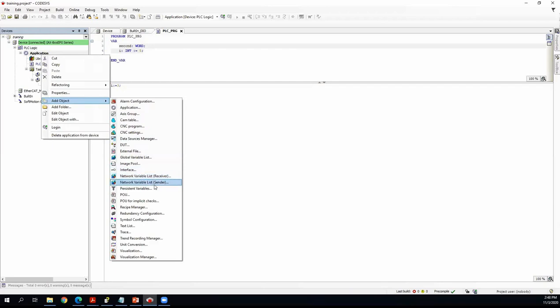This, for instance, is the Ethernet IP communication interface for object-oriented programming. This one is for OPC UA. So there are many tools and apps that you can use. For another program, we need to create a POU. POU is a term that comes from IEC 61131. It is the program organization unit and consists of program, function block, and function. So there are 3 different types of program units.